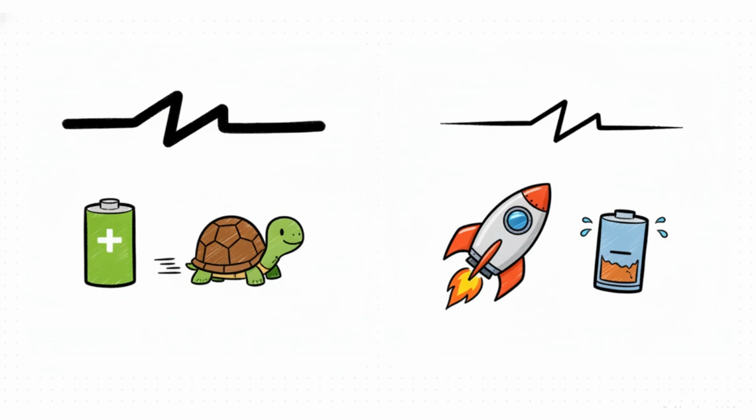It essentially acts like a low-pass filter and bogs down your communication speed. On the flip side, a low-resistance pull-up charges the line lightning fast, which is great for high-speed data, but it's going to burn significantly more power every single time a signal drops low.